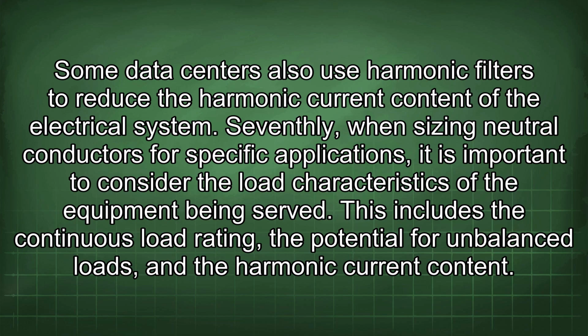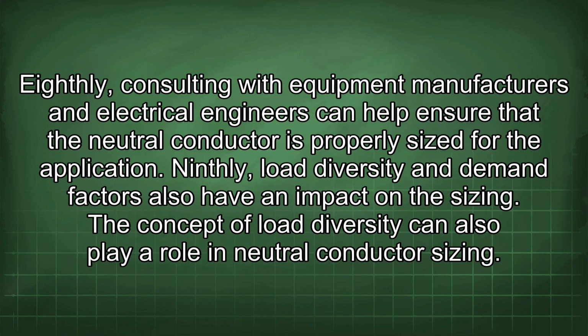Seventhly, when sizing neutral conductors for specific applications, it is important to consider the load characteristics of the equipment being served. This includes the continuous load rating, the potential for unbalanced loads, and the harmonic current content. Eighthly, consulting with equipment manufacturers and electrical engineers can help ensure that the neutral conductor is properly sized for the application. Ninthly, load diversity and demand factors also have an impact on the sizing.